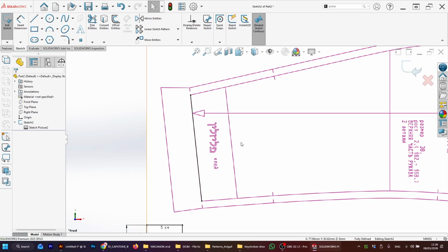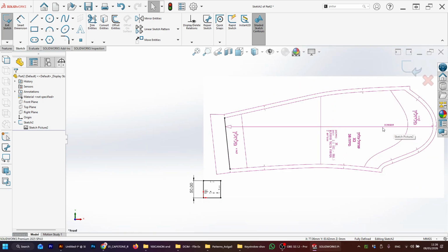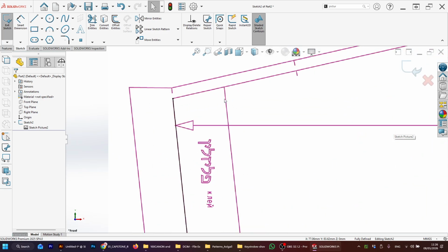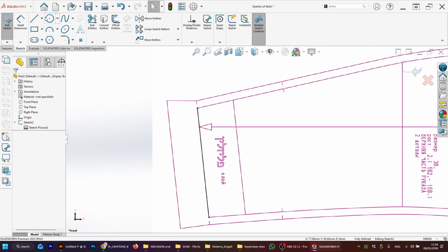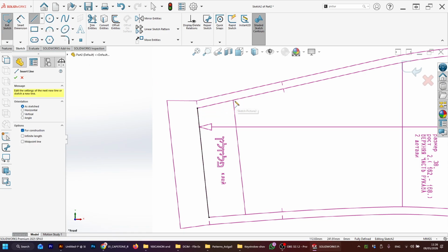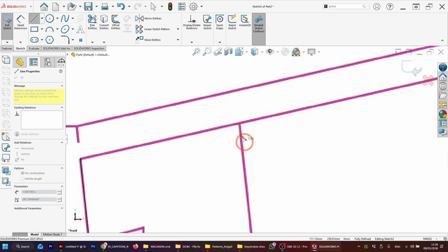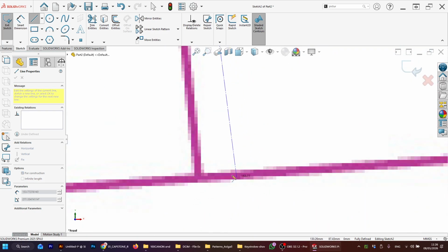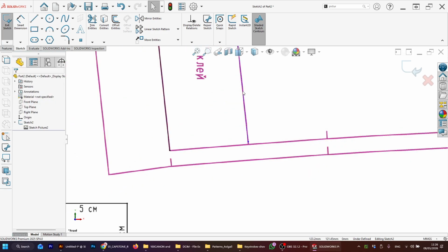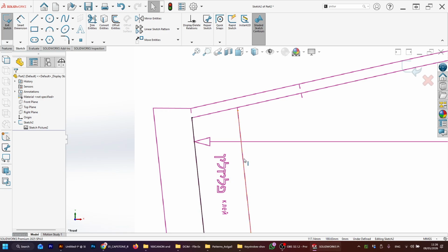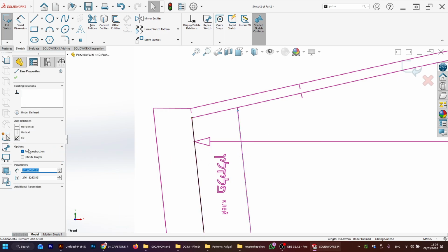If you want these lines that you see here, because they are important for you, but they are not part of the sketch, you can use the center line. So anyway, I get closer. Just a good opportunity to show you something. On purpose, I will do it a little short. Okay? And then I will show you how to make it perfect. But at least now I have a line. It's exactly in the correct angle. I can click on it, fix it.